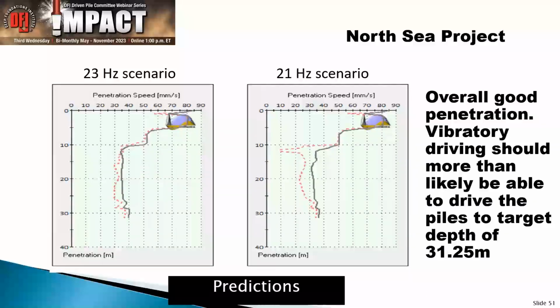Out of the 8 piles, and again, I'll be honest, 6 were a success, 2 were not. With the 6 cases, we were able to get the pile into the ground with the vibratory hammer. At the same time, honesty forces me to say that those piles were for boys, so no real vertical load on this whole thing. We're not there yet that we can say we just blast our way through and then get a capacity prediction.